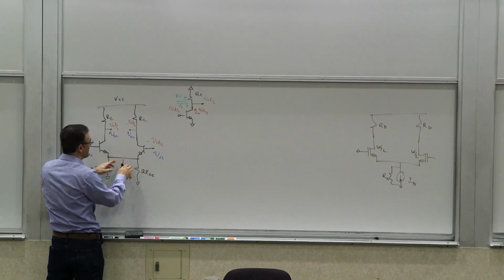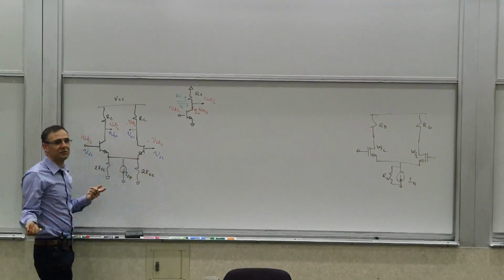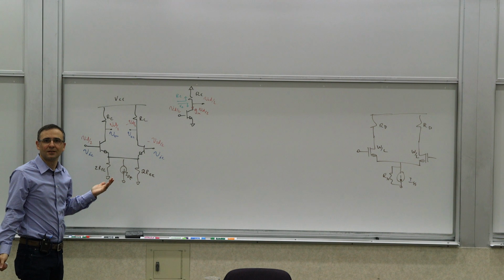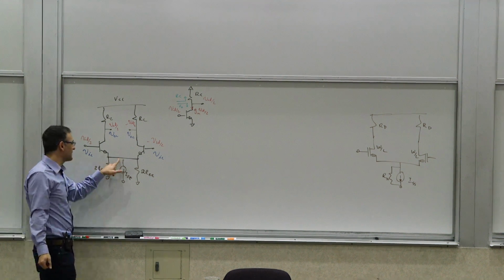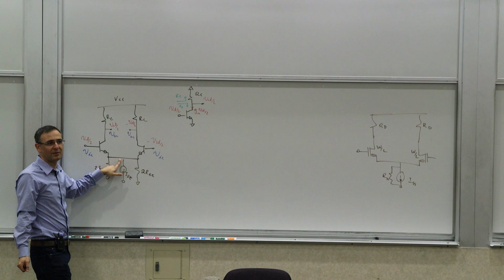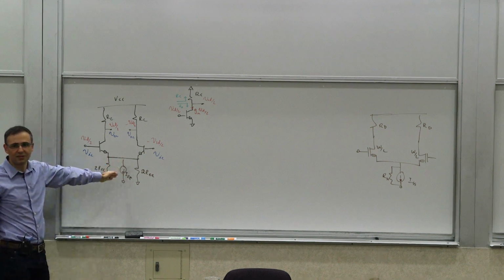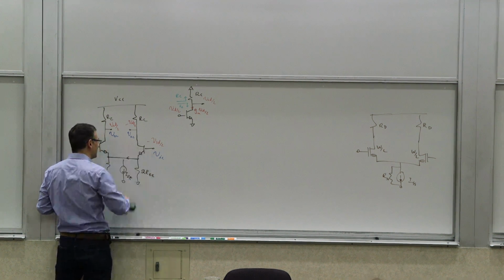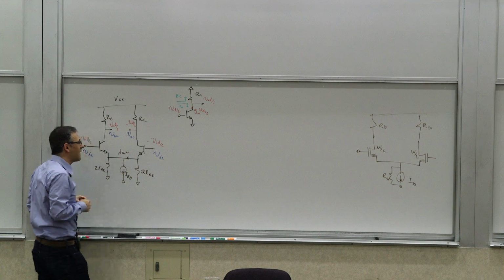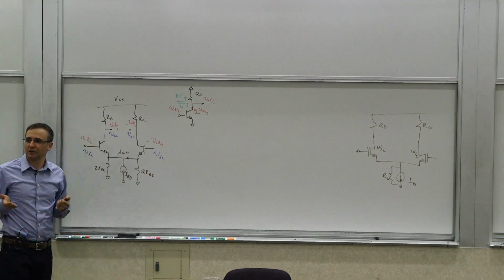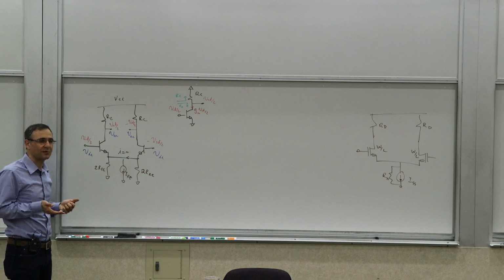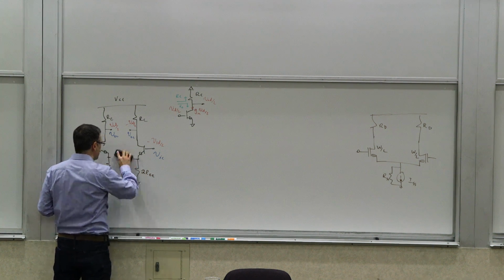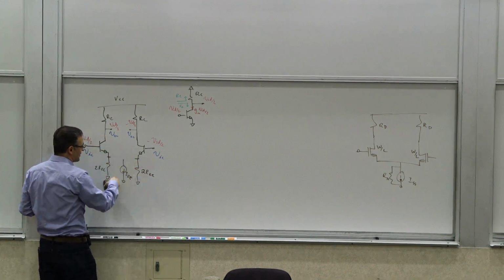When this disappears, the question you need to ask yourself is: which way is the current flowing, from left to right or right to left? The answer is that it can go either way. The only thing that satisfies that and the image in the mirror is 0. So this current has to be 0, small signal rather. And if it's small signal 0, then you can replace it with a current source of 0 value by the substitution theorem again, which means you have open circuited. So you can open circuit this and nothing will happen. Of course, from a small signal perspective, this will be gone anyway.